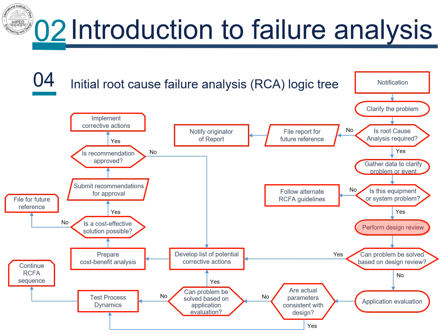The first question is, if the problem is solvable based on design review, in other words if it is a design-related issue, and if the answer is yes, shortcut is in the development of corrective actions. On the other hand, if the problem cannot be solved through design review, proceed with application evaluations and question if the actual parameters are consistent with the design. The yes answer would lead again to a deeper analysis and RCFA sequence, and now would instigate another question, which is, can a problem be solved based on application evaluation?